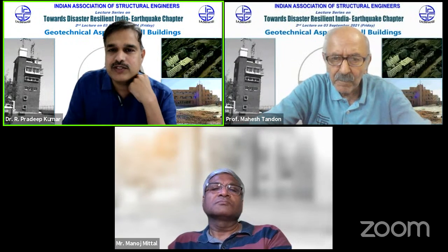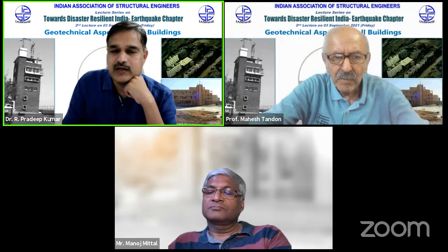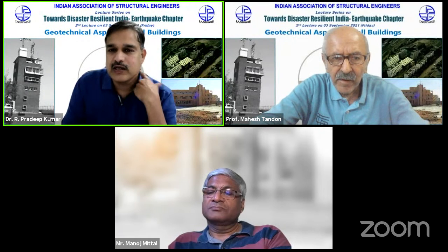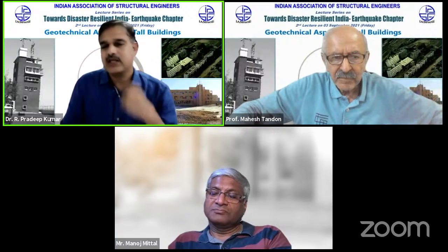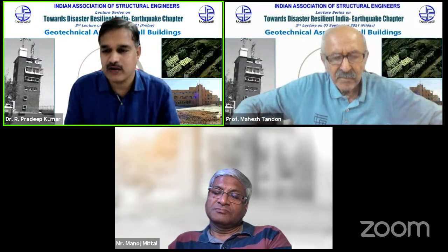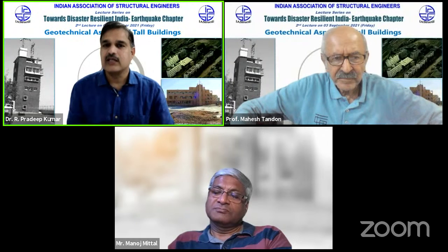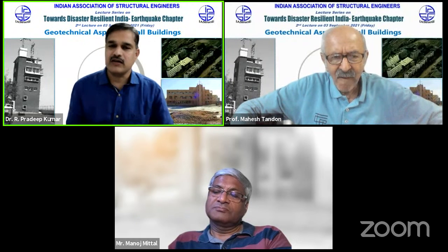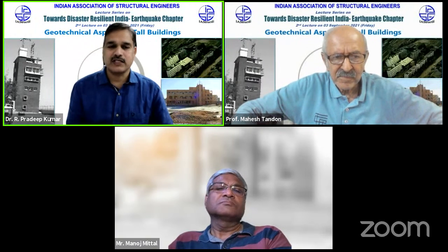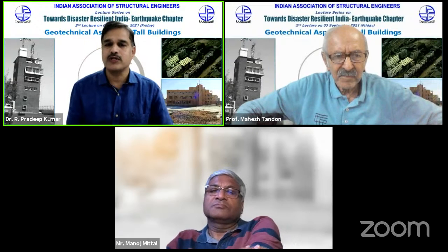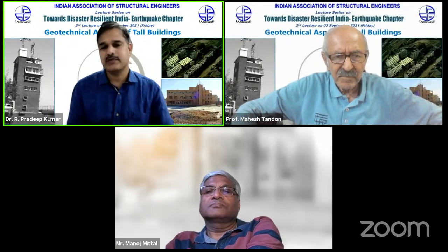So deformation from shear, bending, and rocking have been added. Is it okay considering that during an earthquake, the building may have geometric nonlinearity, and soil might not deform uniformly? Yes, there is a possibility of geometric nonlinearity maybe occurring first. But we can add whatever is the predominant deformation, that is bending and rocking. So these also will get added. But which one will start first? It depends on the type of ground motion which the building is experiencing.